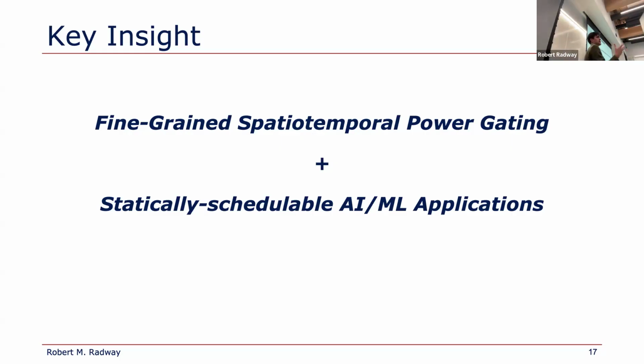It's a sequential process, right? You have this depth of network, and it may be many layers deep, but for each layer, you only read a subset of your memory. That subset of your memory is the only thing you're using for that point in time, and then you go to the next layer, and then the next layer, and the next layer. So only for any slice of time while you're actively computing, you only need a small portion of the total memory, and there's a huge energy savings to be had by taking this idea of power gating and doing that at that very fine granularity.